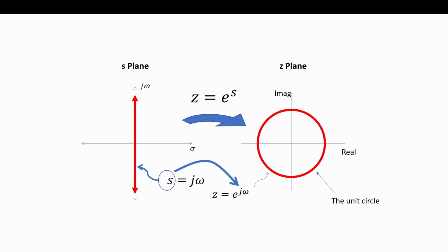So when you see the z-plane and you see this unit circle, that's the same thing as the j omega axis. So anything we know about that or learn about that, for example, one thing you'll learn as you do more of this is those poles, if they get closer and closer to that j omega axis, that represents a high resonance, right? And you can kind of picture it. That pole was a tent pole, right? If we get closer and closer to the j omega axis, our frequency response is going to go way up, right? So it's the same thing you'll see here as we deal with poles and zeros inside here. As they get closer and closer to the unit circle, there are higher Q resonances. A good takeaway in terms of that.